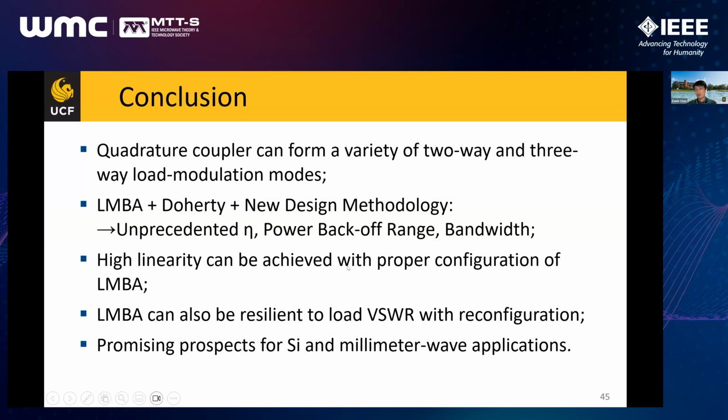High linearity can also be achieved with the proper configuration of the LMBA, which can also be made very resilient to load mismatch VSWR with the bias reconfiguration. It also offers promising prospects of scaling to microwave applications in silicon technology.